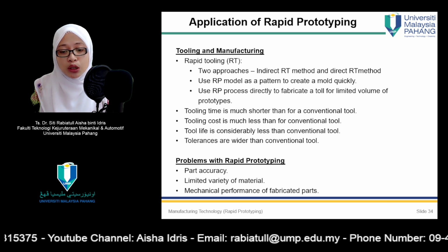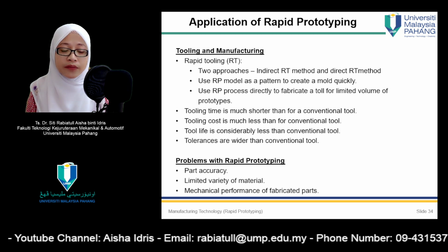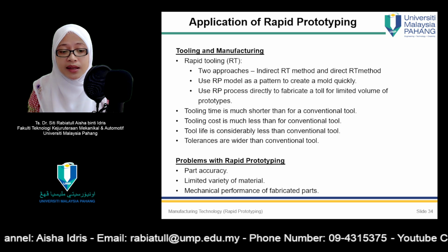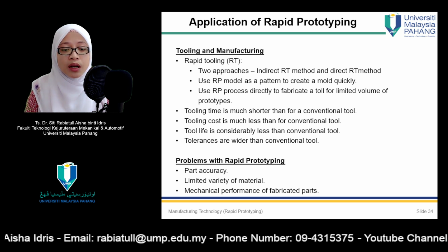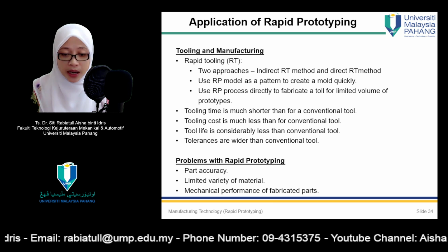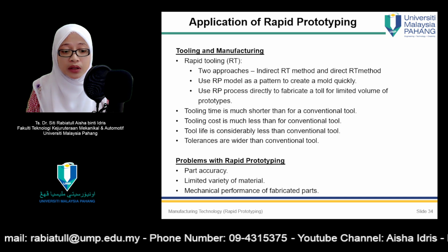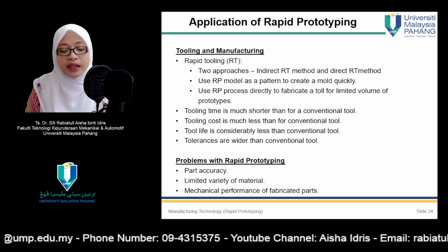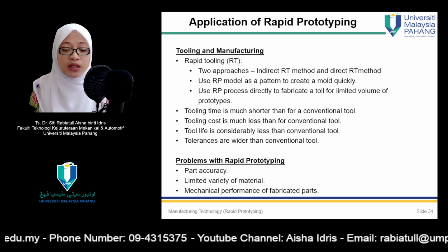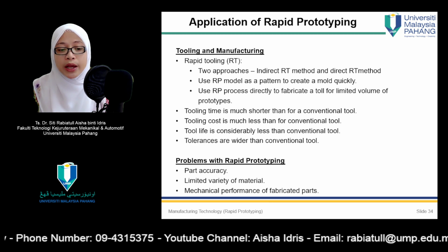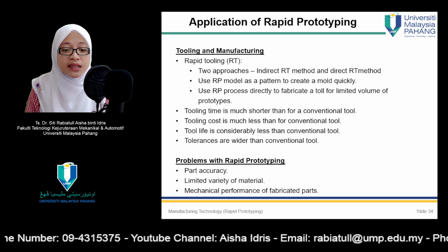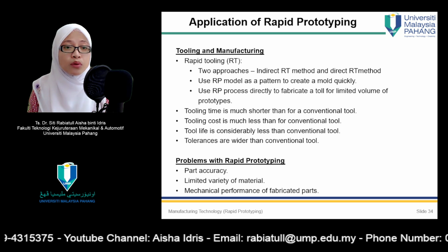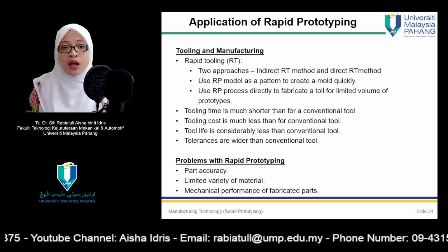Mathematical errors include approximations of part surfaces used in RP preparation and differences between the slicing thicknesses and actual layer thicknesses in the physical part. The latter differences result in z-axis dimensional errors. And an inherent limitation in physical parts is the steps between layers, especially as layer thickness is increased, resulting in a staircase appearance for sloping part surfaces.